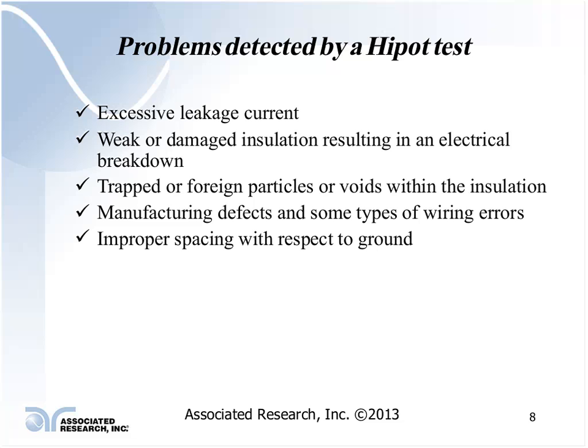The product was not necessarily faulted, but because it wasn't grounded, the leakage current ended up going through the girl, and she died as a result of coming in contact with that light, trying to move it after just getting out of a pool. This happened a few years ago down in southern Illinois.